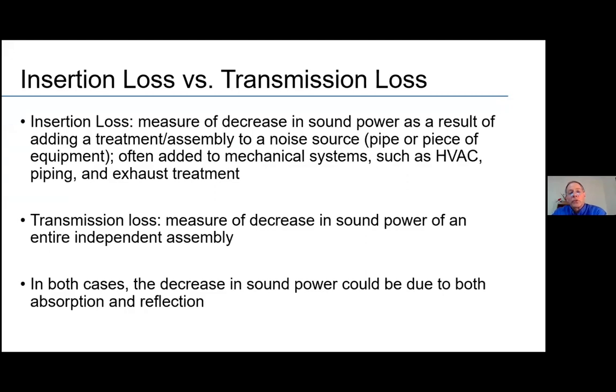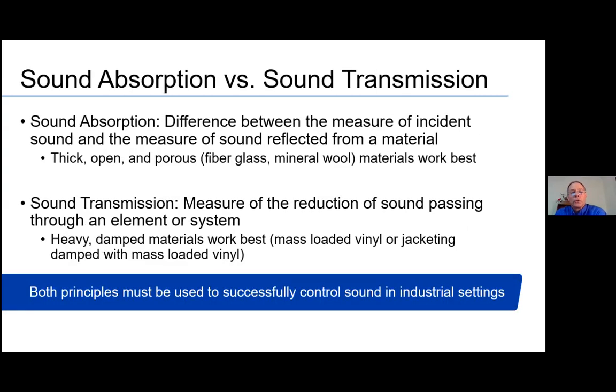So again, just doing a quick comparison of the two, insertion loss is a measure of the decrease in the sound power as a result of adding a treatment, whereas transmission loss is a measure of the decrease in the sound power because of an assembly that's applied. And in both cases, the decrease in sound power actually could be due to both absorption and reflection of the noise. And again, that's going to come into play depending on the frequency of the sound that you're trying to address.